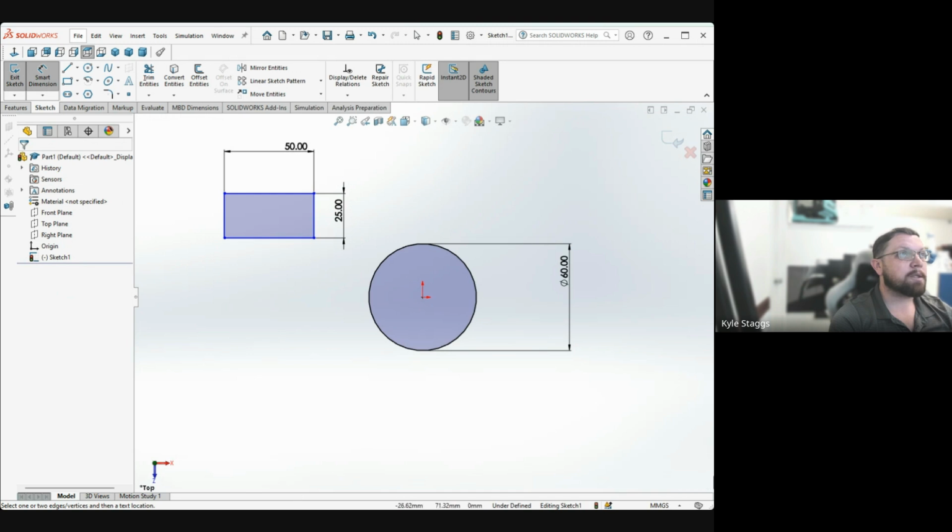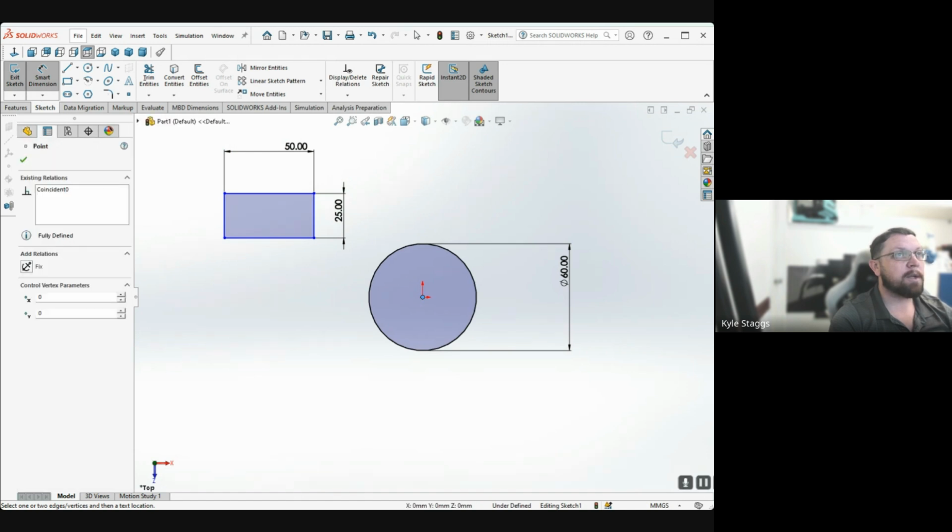The problem is the software doesn't understand where this is yet relative to the origin or the coordinate system that we're using. So as a dead minimum, we have to select the point of the origin. In this case, we're not drawing a continuous line. We need a point from the origin. And in order to really properly define, depending on how we drag it out, this is why I wanted to show you an example like this.